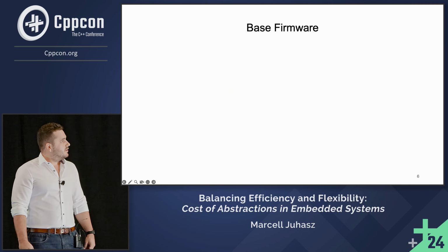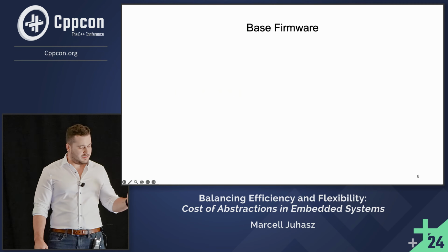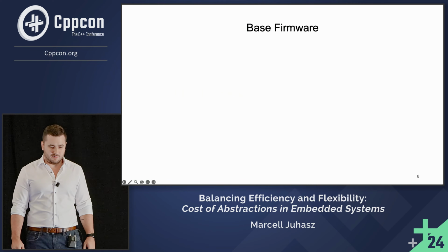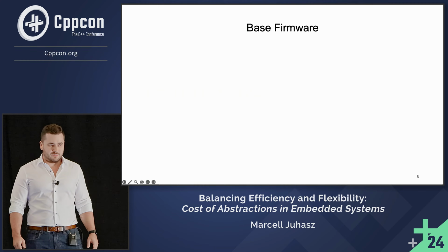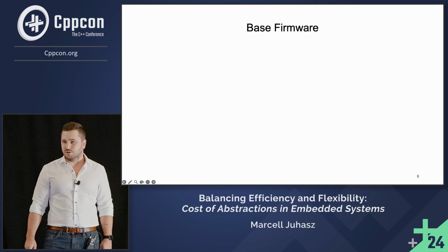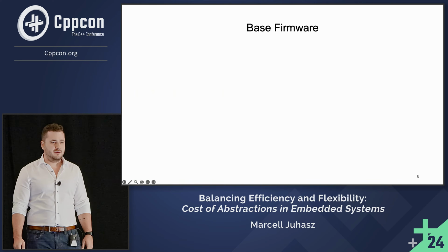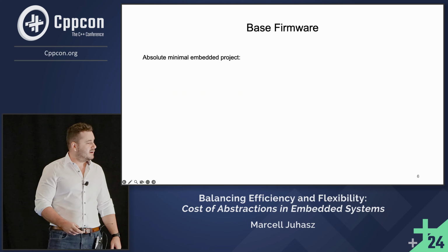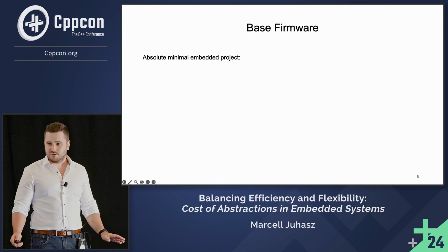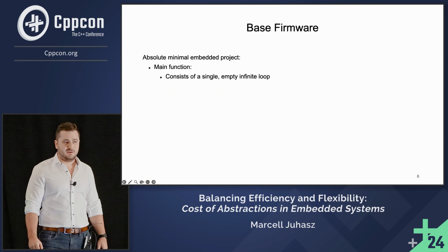So before we jump into the main topic, I would like to just briefly introduce the concept of the base firmware, which will serve as a basis for comparison for both the binary size and the disassembled binary. I simply define the base firmware as the absolute minimal embedded project consisting of nothing but a main function with an empty infinite loop.